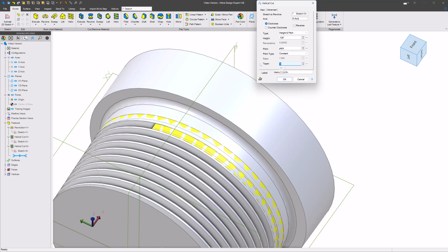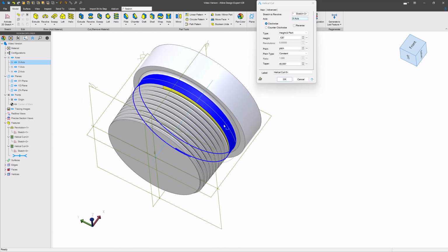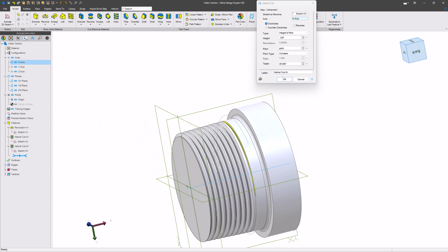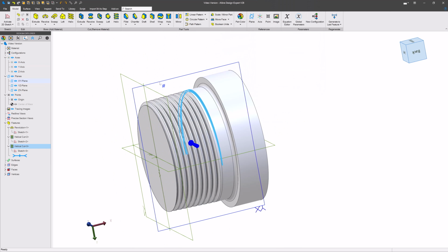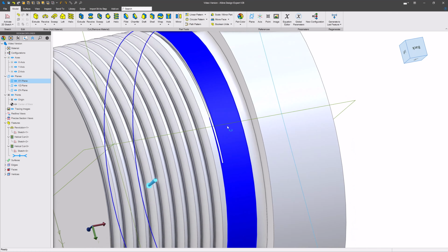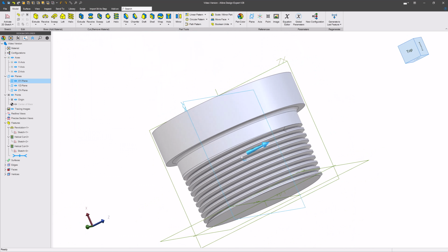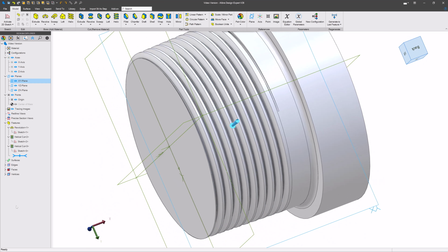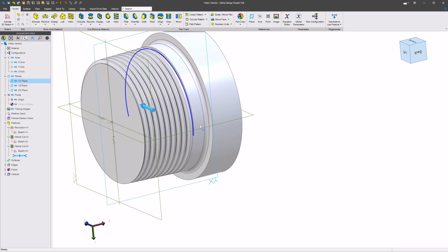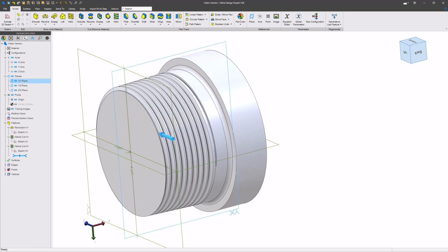And then our taper needs a little bit of work. So we're going to say, well, actually not our normal taper angle, but we'll do something large like 45 degrees. And there we have a runout that I don't believe cuts anything that we don't want cut. And we have a nice gradual runout that I think looks a lot more realistic for a thread like this. So, nice simple runout if you'd like to add that. And so that should be our external NPT thread.